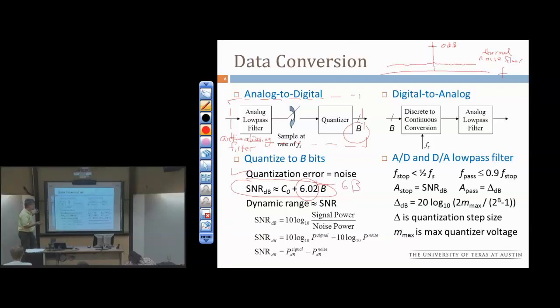And now this is the case for your data converter in lab. We went through this. So I have a 16-bit data converter in lab that you're reading from. The A to D, this is the analog interface chip, the AIC chip on your board. You read 16 bits from the A to D converter, but only the first 13 are good. The upper 13 most significant bits are accurate, and the low 3 bits are noise. But it's easier to read 16 bits than 13. What do you do with 13 bits? Everything's working with multiples of 8 bits internally on the CPU and in memory.